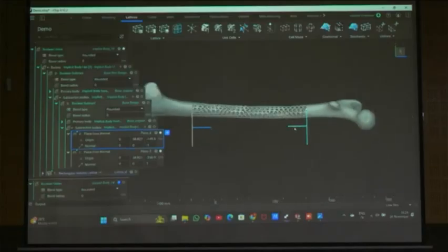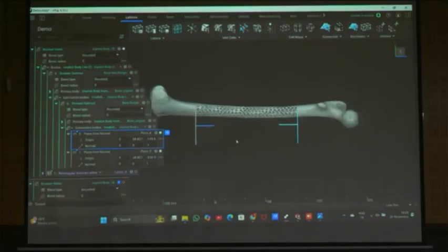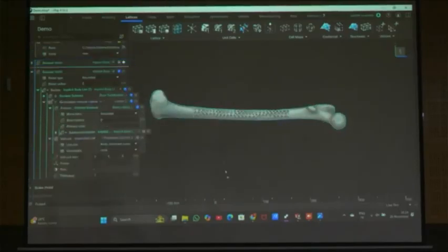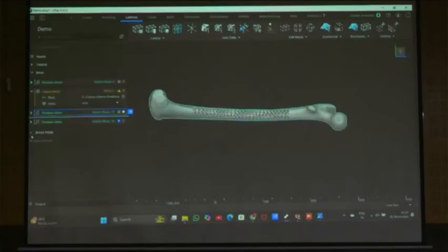You can increase it further so that you will get the bone lattice portion. I randomly put the length and all those things. Like this you will get the bone with the lattice body, okay? The same type of design is already available there, you can get it here. Gradient also it is there. So clear? Then if you are clear, then we can go for the engineering component, that is brake pedal.